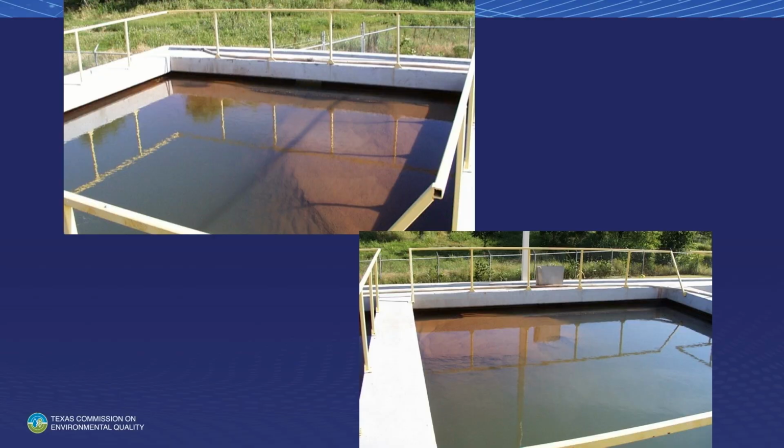And going into a single port with no dispersion wall behind it, you can see that on the west sed basin, all the sludge was built up on this side of the clarifier. Now, to an old West Texas country boy trying to do an investigation, that kind of indicates a little bit of a short circuit inside that basin. And the sludge on the east basin was all built up on that inside wall the same way. And again, I think that basin was just a little bit short-circuited, don't you?